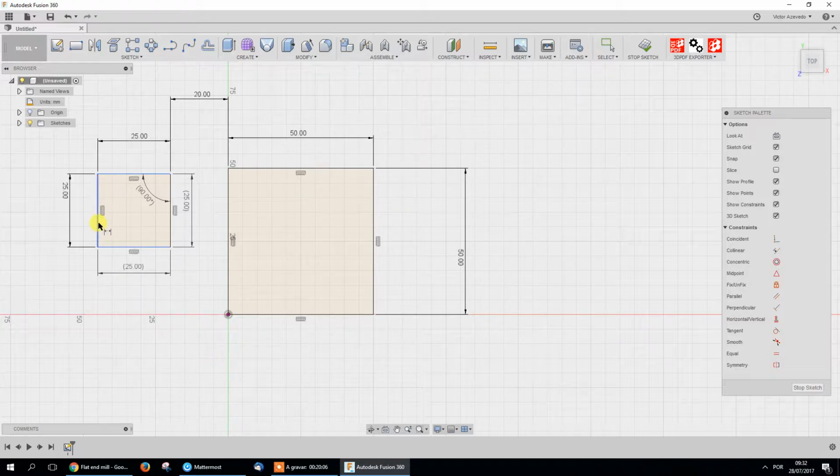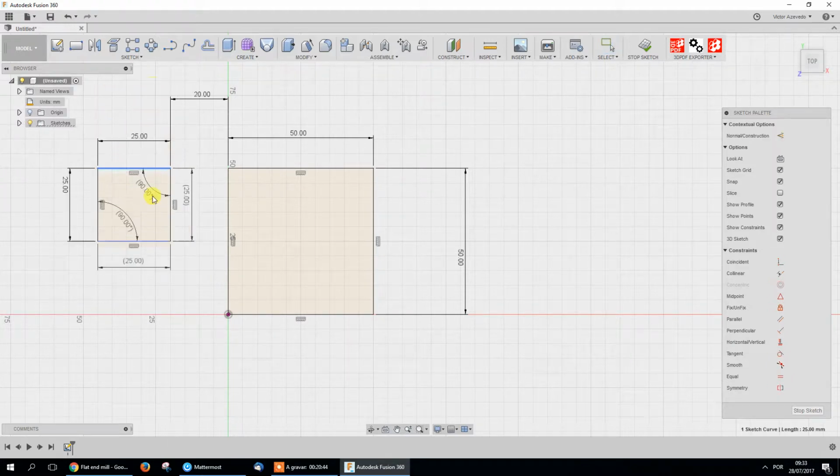So dimension, click here. Just forget this dimension, click here, and it will make the angle. In this case, it's driven. That's why it's on brackets. This line and this line is already black because I can't move to the left or right. They are getting defined by the other square. But this one and this one is still blue. So I don't have anything to lock this.